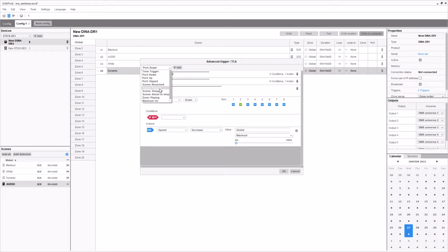For some reason you have another DMX controller, for a conference room, for example, where sometimes you've got a main lighting desk mostly for entertainment or live events, but they're both sending DMX. So you can have the output of the desk connected to the input of the DINA, and the operator will have the possibility to send a specific DMX channel to the DINA to reduce the intensity, for example, of the facade or whatever is controlled with the DINA. So a lot of options.